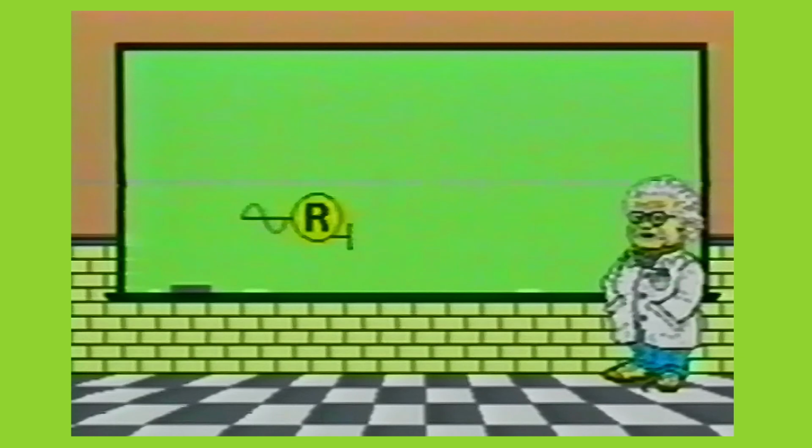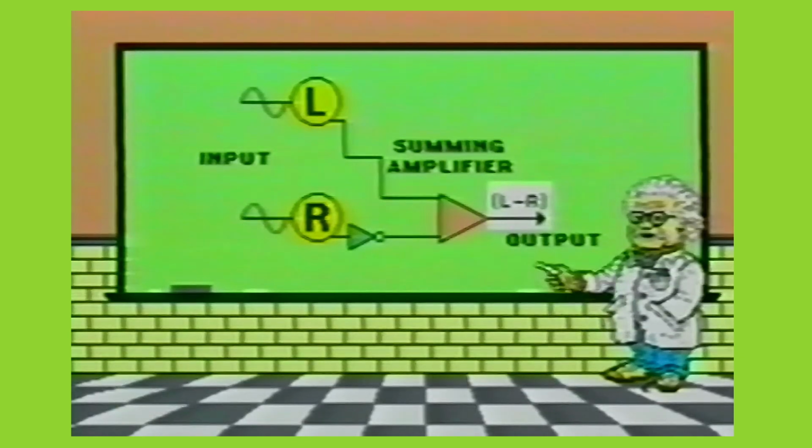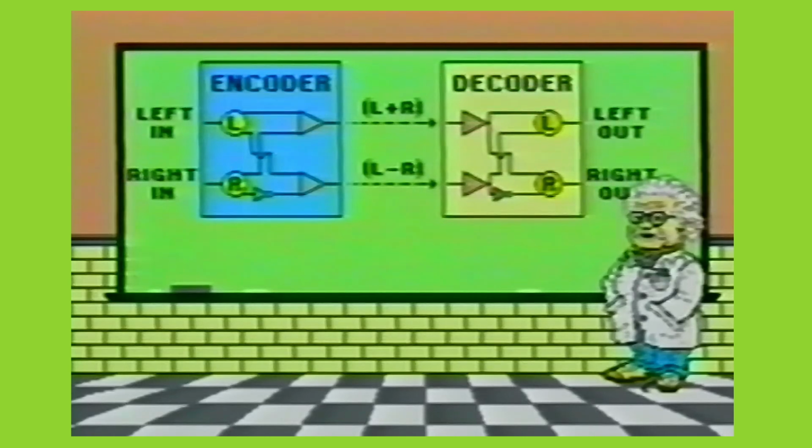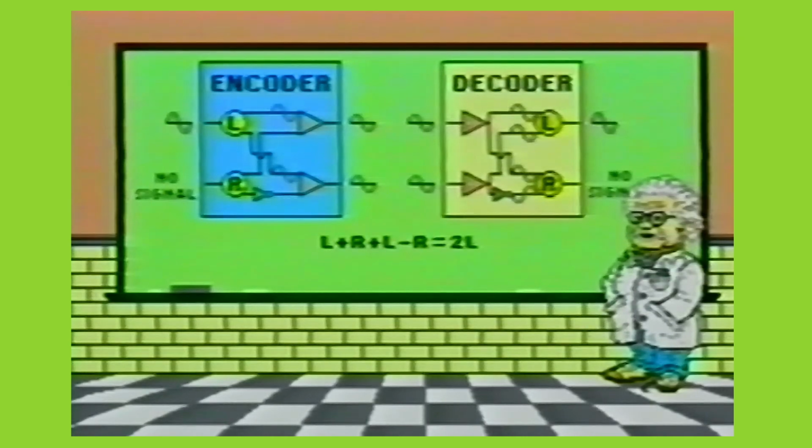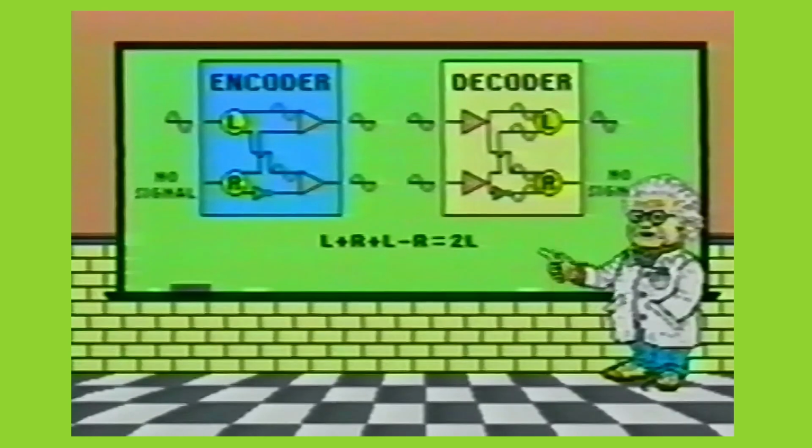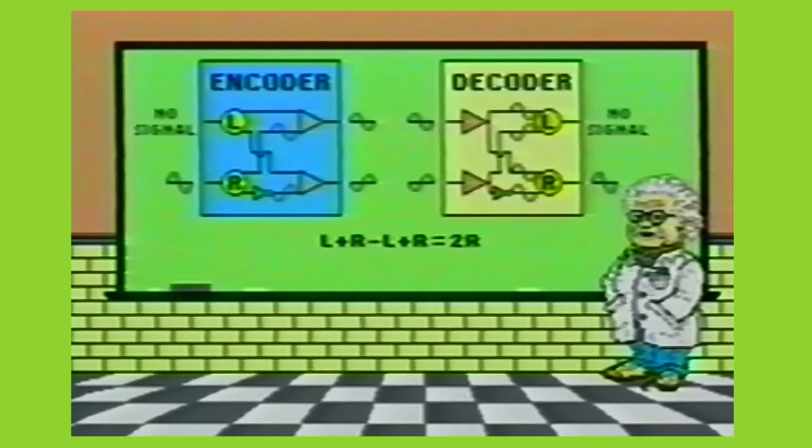The L minus R signal is simply a combination of the L signal with the inverted R signal. A matrix section, whether encoder or decoder, relies upon amplitude and phase variations of at least two different signals to extrapolate the desired waveform. We learned about the extreme waveform conditions which could occur at the encoder and decoder matrices. In actual operation of either matrix, phase relationships should fall in between these extreme broadcast characteristics, reproducing the left and right soundtracks from the original transmitted information.